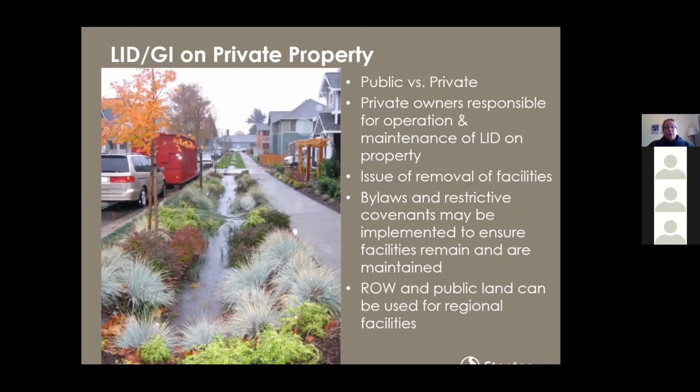You can use bylaws or restrictive covenants to ensure that the facilities are remained and are maintained. You can also look at something like a public utility program, wherein people are charged for stormwater, and having those facilities gives them a credit. So if it's removed, the benefit of having it and having that credit is also removed.